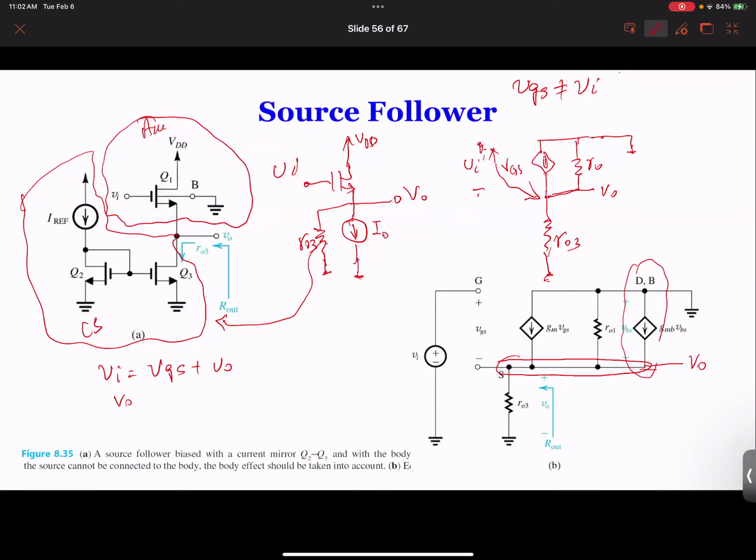It's VO divided by RO3, that's current going out, plus VO over RO1, that's current going out, equal to the current coming in, which is Gm times VGS. And then there's another current, but forget about this current.